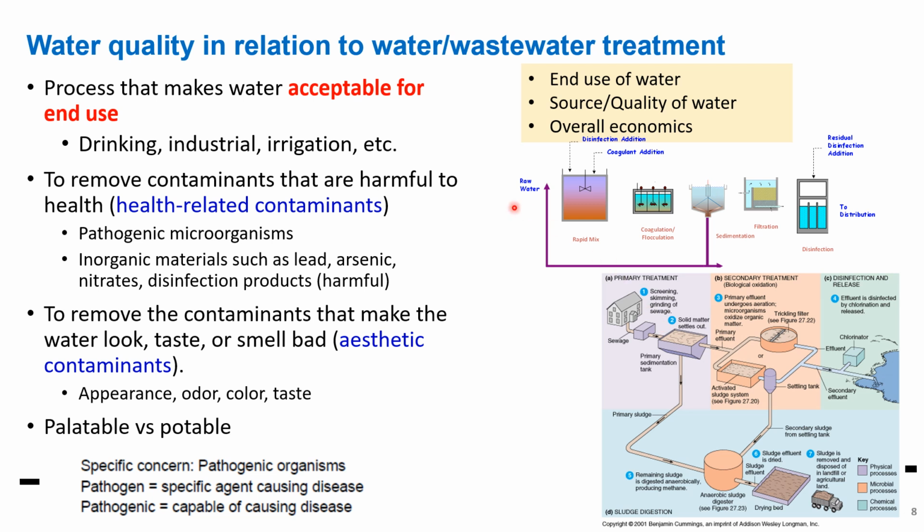So in comparison to wastewater, we need further or more stringent processes, because it contains a lot of biological things and the BOD is quite high. So we will go towards a primary treatment, and then a biological oxidation, which is needed because the BOD content is high compared to this kind of water. So the water quality is different.